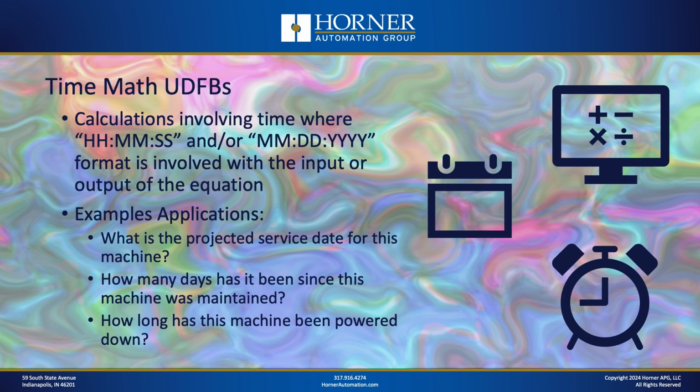All right, finally, our last category is time math user-defined function blocks. These are incredibly useful, and they seem like they should be really simple to do without having a function block, but the reality is the function blocks are real time savers out there. Okay, so what are time math UDFBs? Well, basically, they are function blocks that perform math type operations, but where the operands are hours, minutes, seconds, or month, day, year, or some combination of the above.